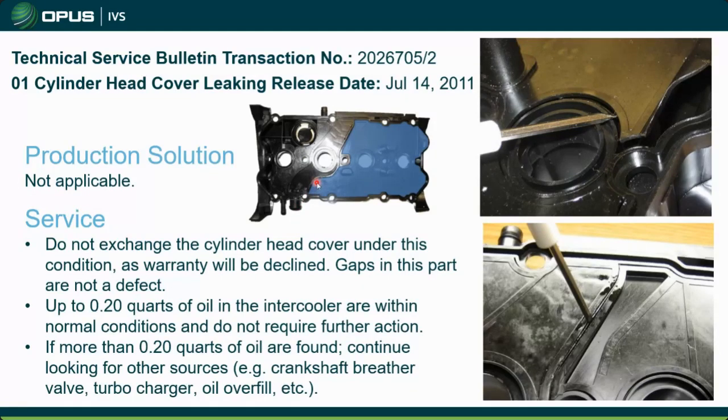Well, the problem is that this system is built using an ultrasonic welding technique for plastic, and I guess they just weren't that good at it, because a lot of these have an issue where the plastic starts to separate, as you can see here with the screwdriver, or right here. And where is that separating? That is separating right along this line here for the venting of your breather.